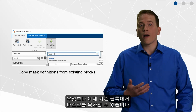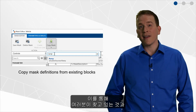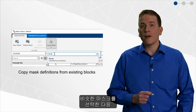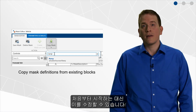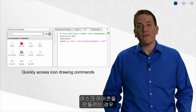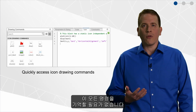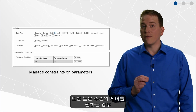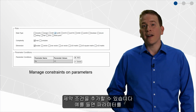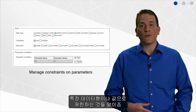First off, you can now copy a mask from an existing block. That way, you can pick a mask that's close to what you're looking for and then tweak that instead of starting from scratch. When you're creating the icon for the mask, you'll have quick access to the drawing commands so you don't have to remember them all. And if you really want a high level of control, you can now add constraints like restricting parameters to specific data types or values.